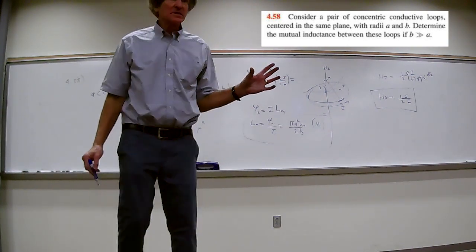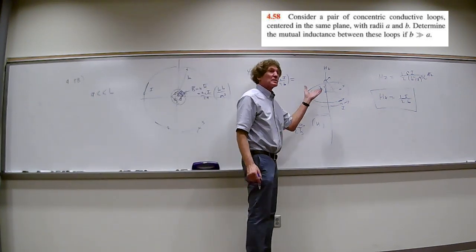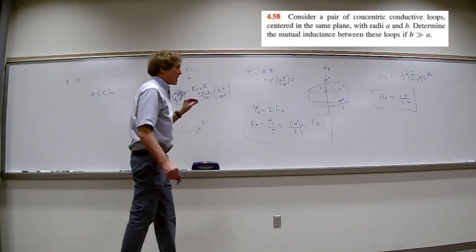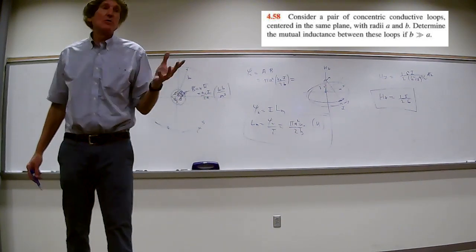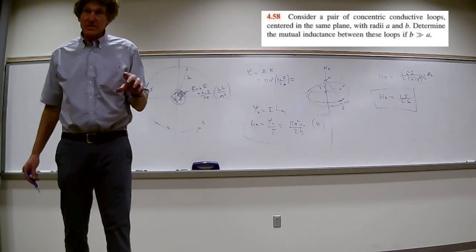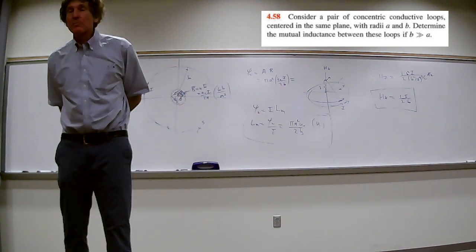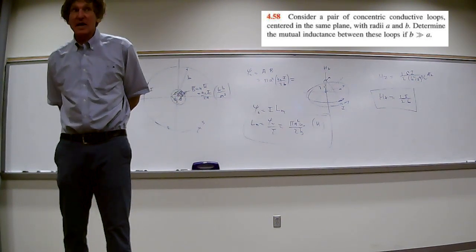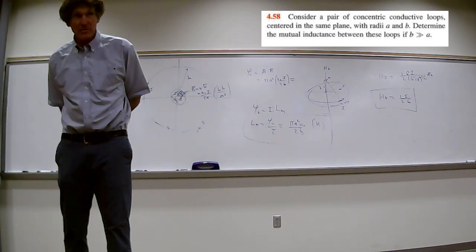Y'all hear me? Now, second question. You know it's proportional to n on the outer one because the flux would keep increasing by the number. What about on the inner one? What happens if it's not 1 turn, but m turns, or L turns? They multiply by L. Y'all follow me? So it's the total. It's a linear property. Whatever happens if I have 10 turns on the inside and 50 on the outside, it would be 50 times 10 would be the magnifying power of those numbers. Y'all follow me, class?